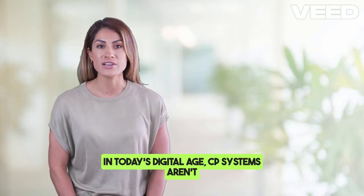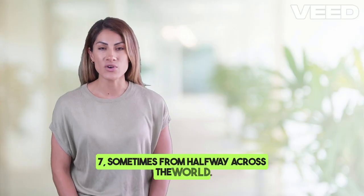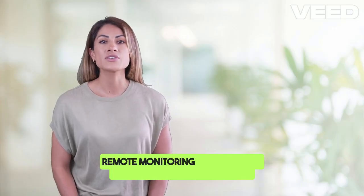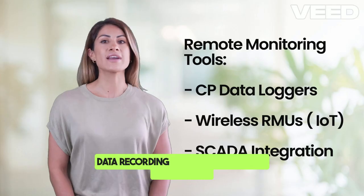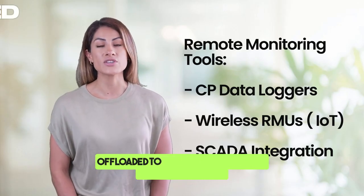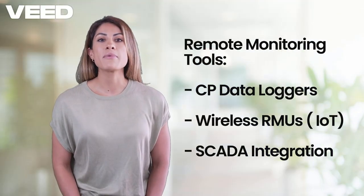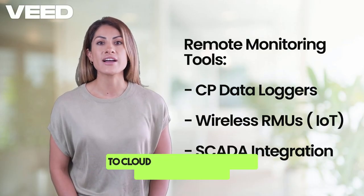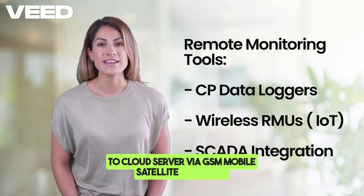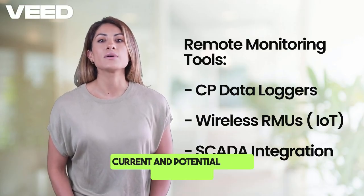In today's digital age, CP systems aren't just installed and forgotten. They're monitored 24/7, sometimes from halfway across the world. Remote monitoring tools: CP data loggers. This records periodic data at test points, which later can be offloaded to mobile or laptop for further diagnosis. Wireless RMUs, remote monitoring units, use IoT devices which send monitoring data to a cloud server via GSM mobile or satellite network. This IoT device monitors voltage, current, and potential.